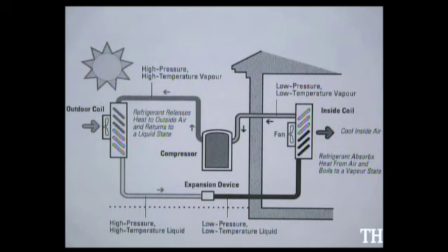The outdoor fan cycles off and the refrigerant warms up the outdoor coil until the ice melts, and it shifts back into the heating mode once it times out and thaws the ice off the outside coil. The heat pump, when compared to electric heat strips, is approximately 3 times more efficient to operate. When compared to gas heat, they are close to the same, but local gas and electric prices dictate the efficiency of each.